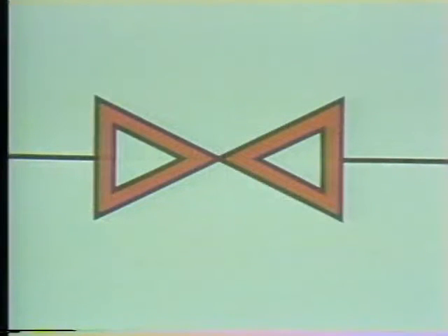In reading prints, there are many symbols that have almost universal meaning. This, for example, is a valve on almost any print. But just as different areas use the English language differently, different manufacturers use different sets of standard symbols. Plants and factories also use their own sets of symbols in their system descriptions. An example of this variety of symbols is that these symbols all represent a normally open gate valve.